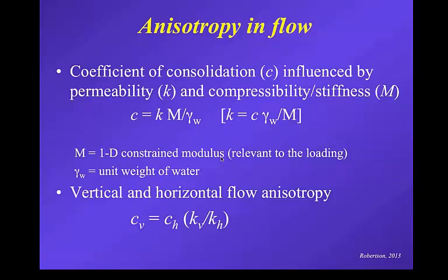Then you've got anisotropy and macrofabric, fissures, etc. Fissures closing initially when you push the cone and then opening a little bit as you recompress. Influence of non-horizontal dissipation, soil disturbance. If you've got sensitive soils, you get a smearing around the cone, and Burns and Mayne did try to allow for that. They incorporated a smear zone. And then, of course, the filter element potentially becoming clogged in those cases, or not 100% saturated. So a lot of uncertainties.